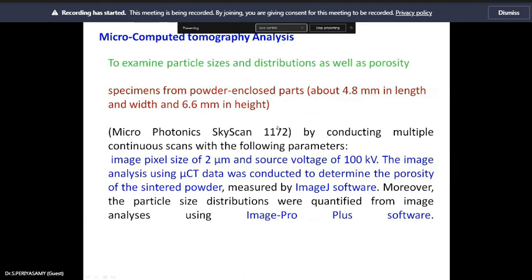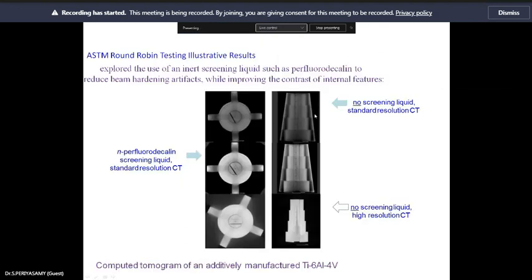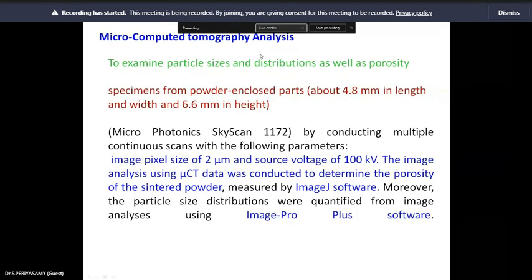Cracks are another major problem. The cracks commonly originate from the high temperature gradient between the melt pool and the surrounding solids, which leads to excessive thermal stress and rupture. The previous layer also has strain because of the uneven cooling, one having a tensile and another having a compressive stress, and then you have a problem. So the scanning or depositing you have to regulate, and then you have to maintain the temperature.